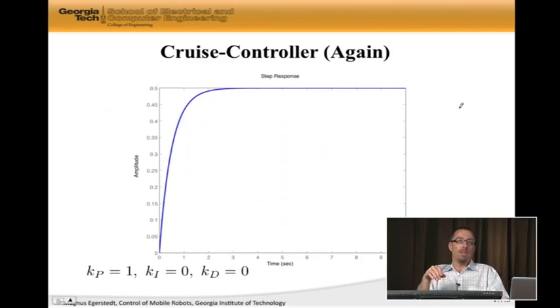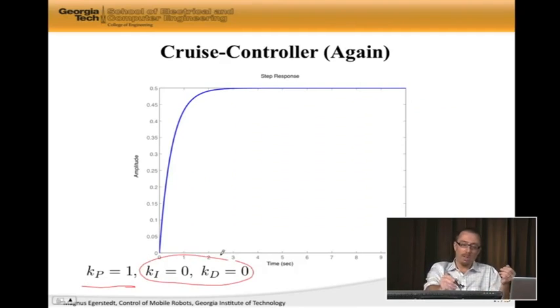So if we start with our friend, the P regulator, so we have Kp equal to 1 here, and all the other gains are 0, then, well, we don't actually make it up to 1. We only make it to 0.1. This we had already seen. So the P part by itself was not enough to both be stable and achieve tracking.